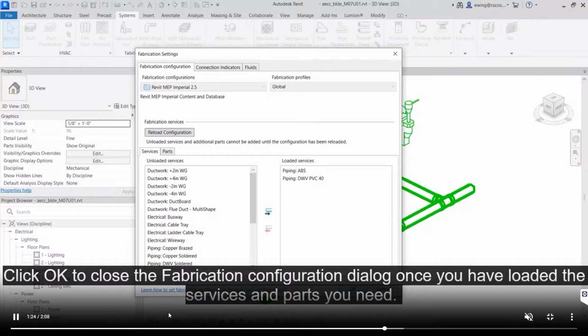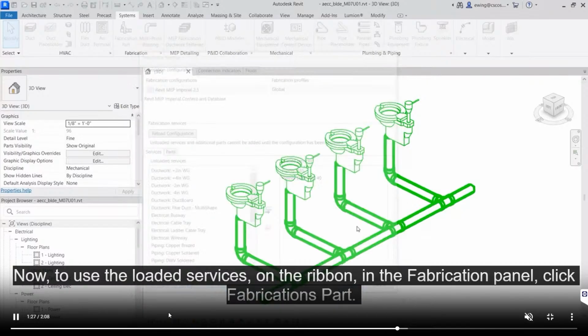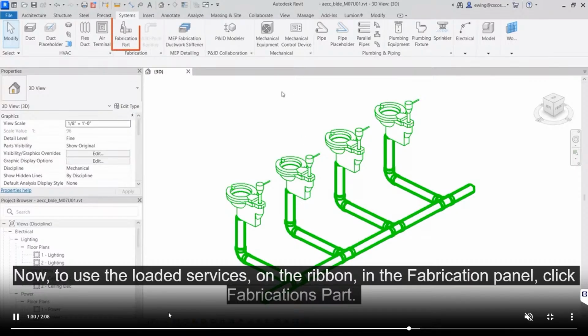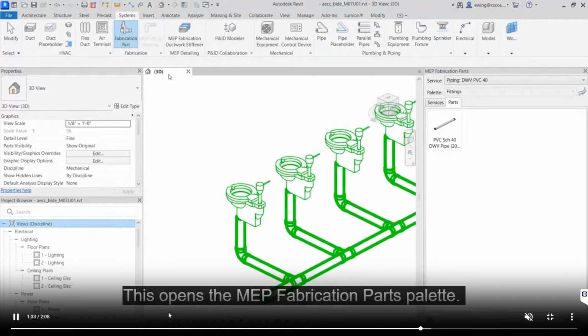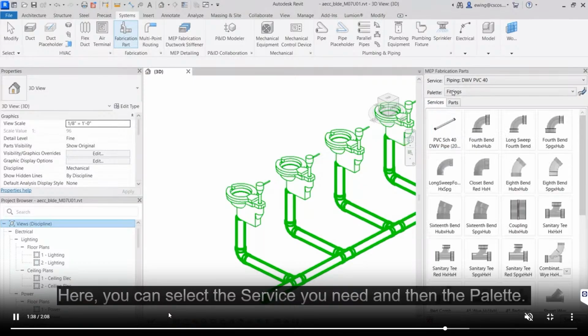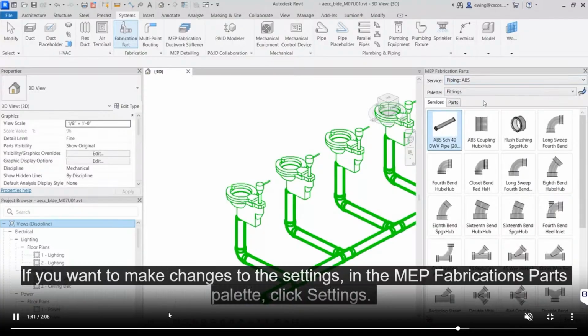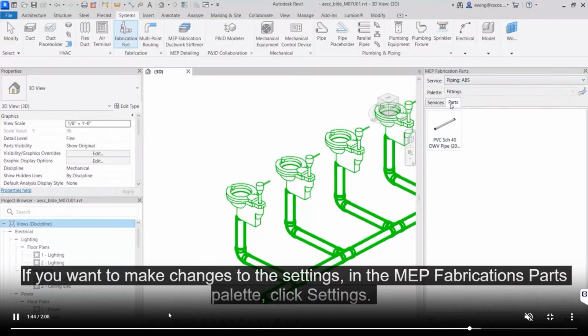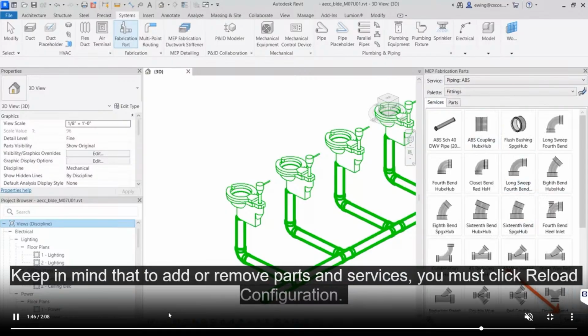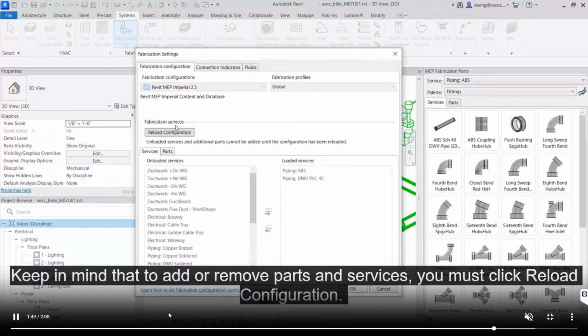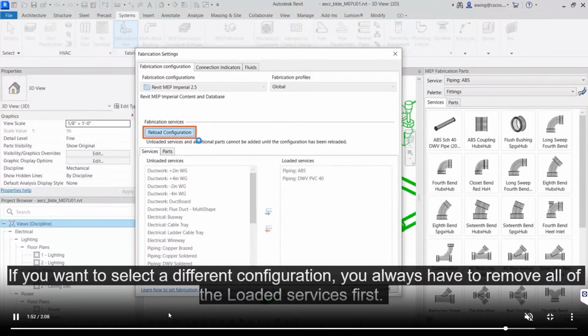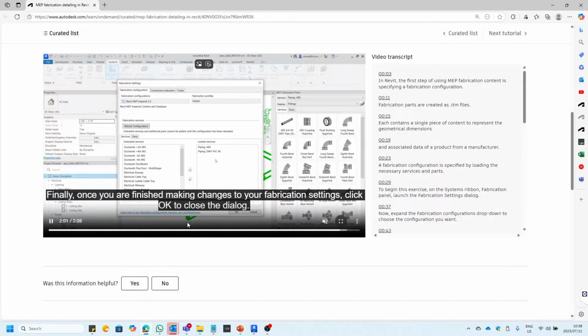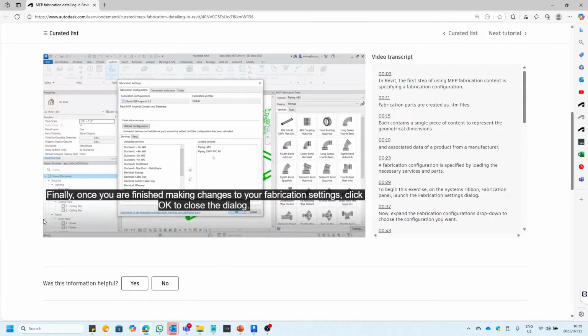So it's not done so often on a design side. It should be, as far as I'm concerned. You should actually be designing using real components ultimately, but it's also employed by the manufacturers themselves. So quite a common thing is for a Revit model to be sent to a manufacturer, and then the manufacturer will apply the fabrication parts onto the model elements within the Revit model and spool it onto these spools. So they offer it as a service, and that is then their competitive advantage. But it is quite a brilliant workflow.